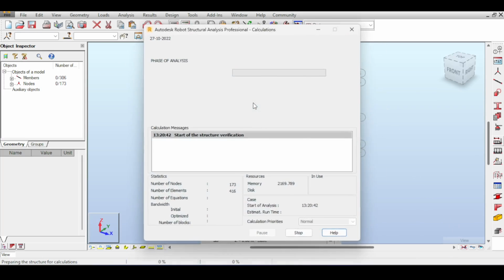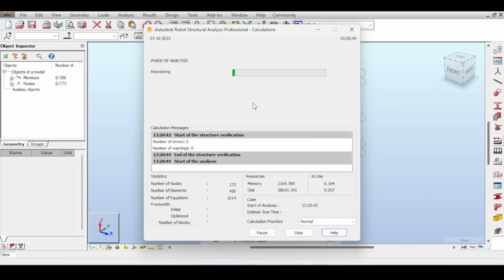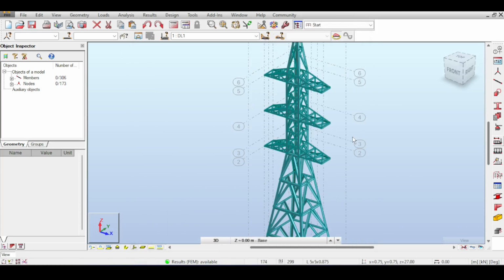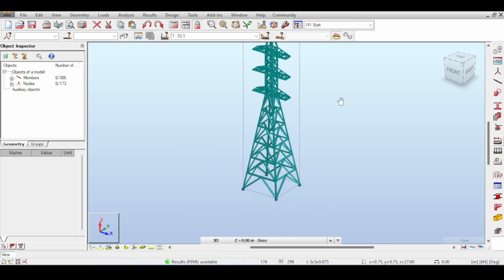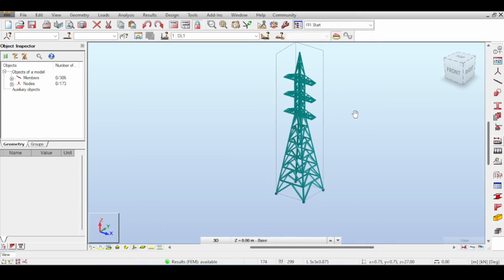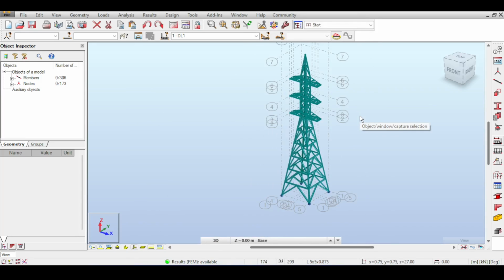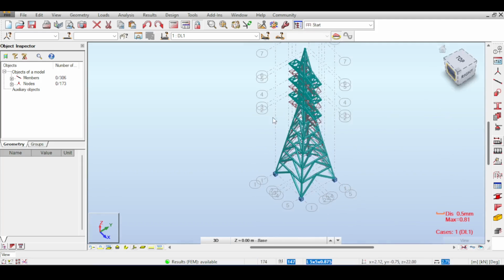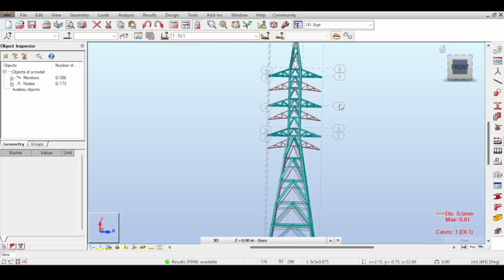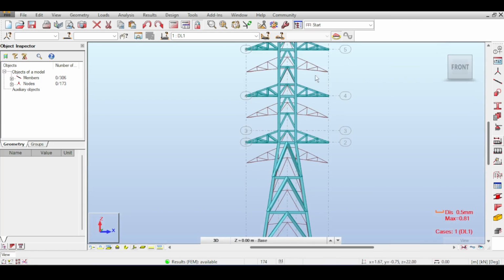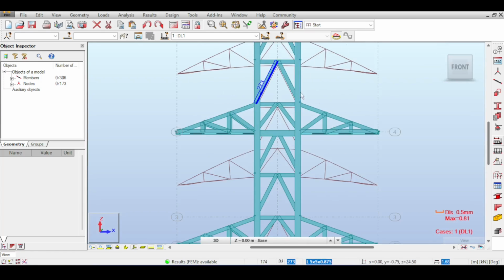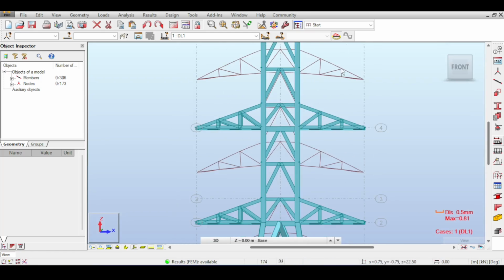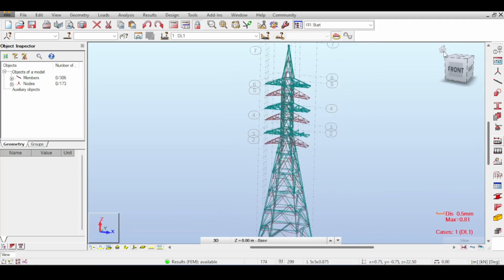I just run the analysis very quickly to make one final check before I save this to continue it next time. Also, I'm thinking to upload this as an attachment to the video. I'll think about this. I think I will upload this just for you to see. So okay, deflection shape, yeah, I think it makes sense. Now you see this time the deflection, of course it's not normalized, but you can see deflections here are much better because there is no bulging in the column because you have stiffened it in the bending direction.